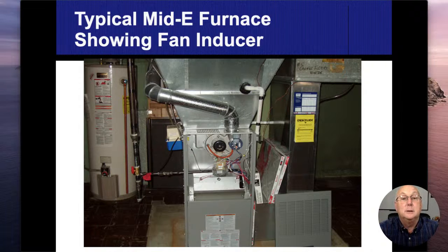Right, this is the gas. We do have gas pipes here on the left coming in here. And so we know we have to have a 6-inch clearance to our single wall pipe that goes up in here. And this orange hose that we're looking at there, that's what connects my inducer fan to that pressure differential switch. And as long as that fan's spinning, I'll be able to create a positive pressure, and this switch will sense it.